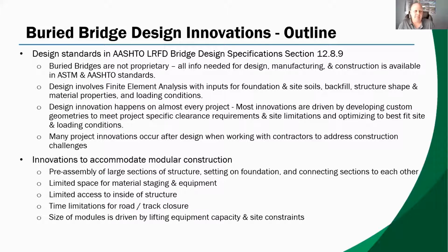These structures are not proprietary. Everything that anybody needs for design, manufacturing, and construction is available in AASHTO and ASTM standards. So there's nothing preventing any agency from specifying this specific material. It's just up to everybody whether they want to invest in being able to learn how to design it and manufacture it. The design of these structures requires finite element analysis, which includes inputs for foundation and site soils, backfill, the structure shape itself, along with the material properties and loading conditions.